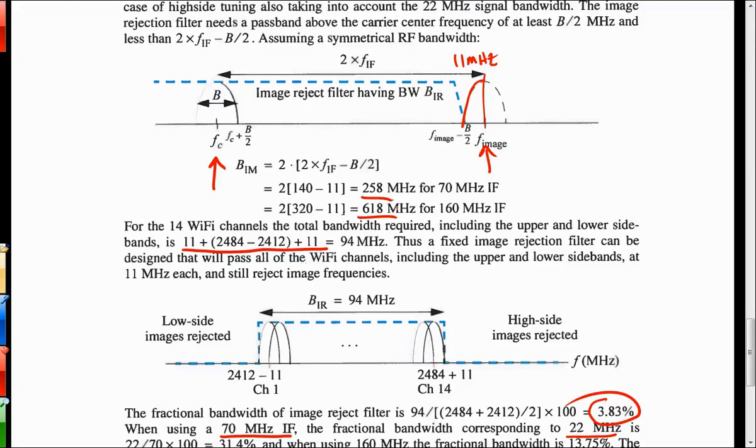So if it was perfect L and C, it would be a very sharp passband because the Q would be very high, because R is essentially infinite. But when you have the R present, then the bandwidth spreads out. And when you have resonators that have a lower Q because the R is present, then trying to build a narrow fractional bandwidth filter becomes very difficult.